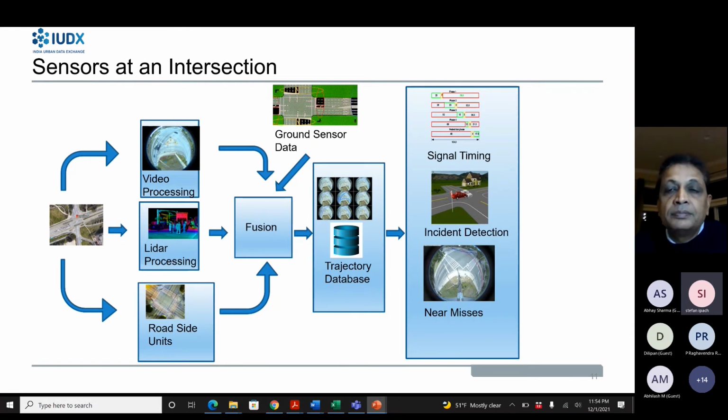Hi Sanjay. So we have come across similar data in India across traffic intersections. But one typical problem that we face here is that we are able to identify the intersection name, but the arms of the intersection or the arms of the junctions is something that we are not able to identify from the data itself. So in the ATCS controller, we have different stages of the intersection control, and these stage numbers are essentially interlinked with the arm names. So we'll have to make a correlation from the ATC system in order to identify the arm names. So we would like to understand how this data looks with you.